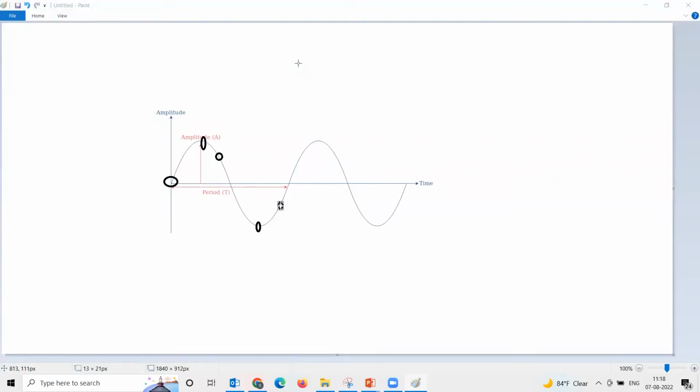So whenever you use these assumptions, the fault current you get is the worst case, or the maximum. And if you change the instant, or if you allow the sources to change during the fault, etc., what you will get is less than this. Your pre-fault voltage may not be 1.1 per unit, and your fault may not be a bolted fault, it might be a fault with small fault impedance, etc. So in reality, the short circuit current will always be less than the value you have calculated in ETAP.